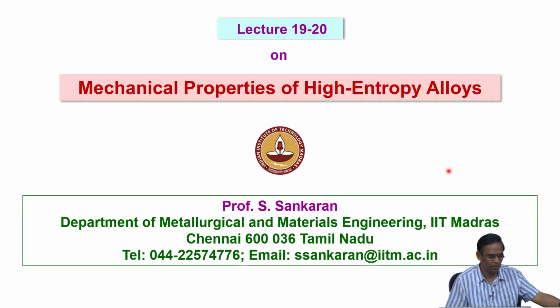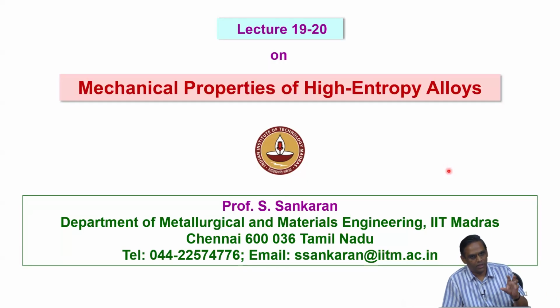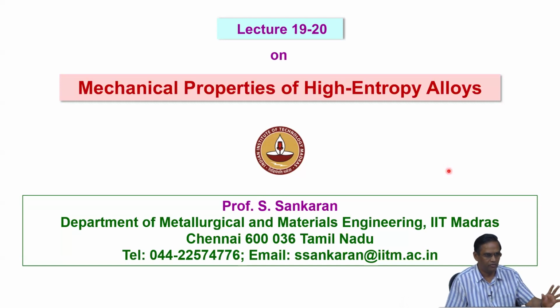than the pure lattice. On the other hand, if you look at any of these mechanisms, because you have already a distorted lattice which has got an additional energy compared to a normal lattice, the dislocation core energy is also slightly different from the conventional pure metal or any alloy, because it is completely a multi-principal component alloy which is completely distorted.